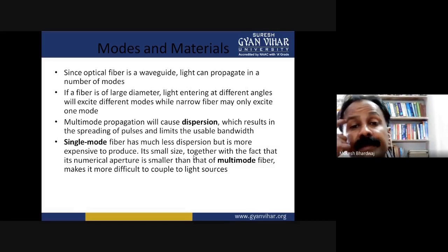Now multimode graded index fiber. These multimode fibers which have a graded index profile may also be fabricated using multi-component glasses or doped silica. However, they tend to be manufactured from materials with higher purity than the majority of multimode step index fibers in order to reduce fiber losses. The performance characteristics of a multimode graded index fiber are therefore generally better than those of multimode step index fibers due to index grading and lower attenuation.